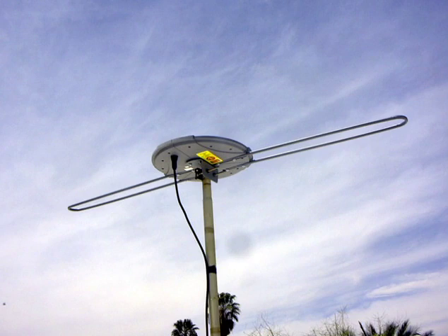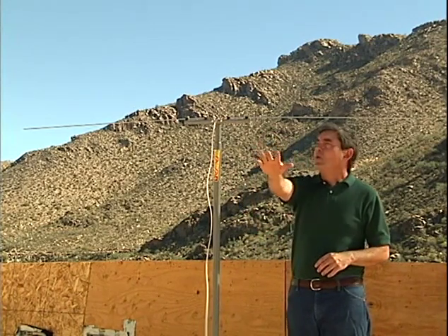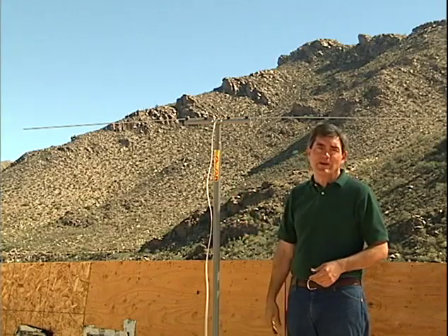Several styles of simple bidirectional antennas are available for attic as well as roof mounting. Bidirectional antennas are best used in suburban areas where all of the transmitters are either in one direction or in opposite directions, and there are few tall structures or mountains in the area.